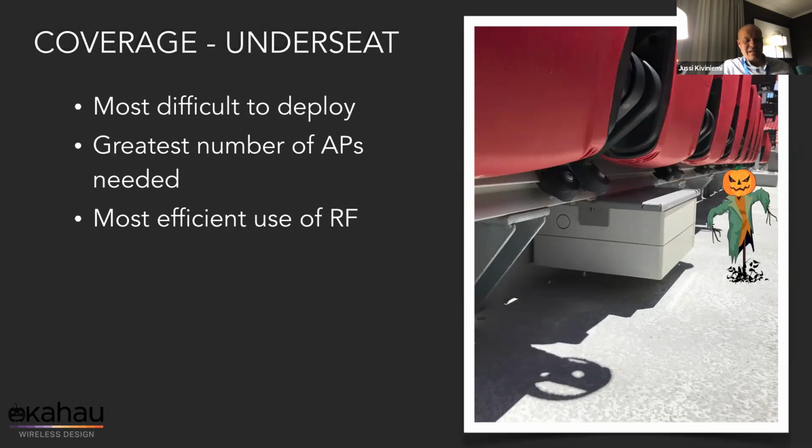What do you guys think? Like the enclosures underseat, have you heard of similar problems? Yeah, I've actually had that happen in an arena stadium that I've worked in, UC. It is very important that the enclosures themselves get installed properly. I've heard other stories from other venues, such as the handrail enclosures, that were installed improperly, where a gasket was improperly installed, or maybe pinched or missing completely from the enclosure, which then, after one good rain, filled the enclosure up, and the access point at that point was a good paperweight.